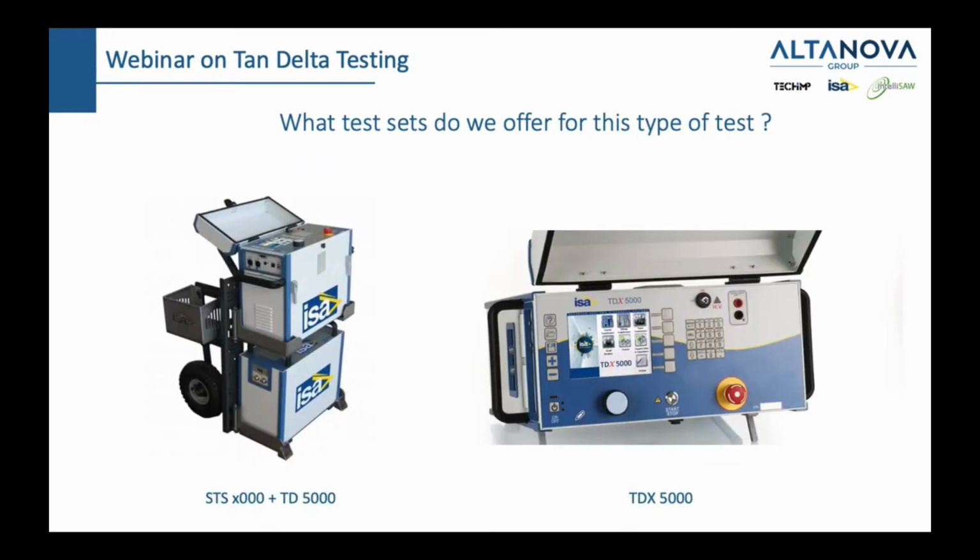So here we have some of our test sets. So let me look at some questions which just came in. Negative PF is a reality in bushings with internal tracking. PF will be negative, yes. Also, tan delta is 1 over omega I RC as per equation. In this case, which is the ideal frequency for measuring the same? So I hope we just answered that. So the frequency should always be the nominal frequency.